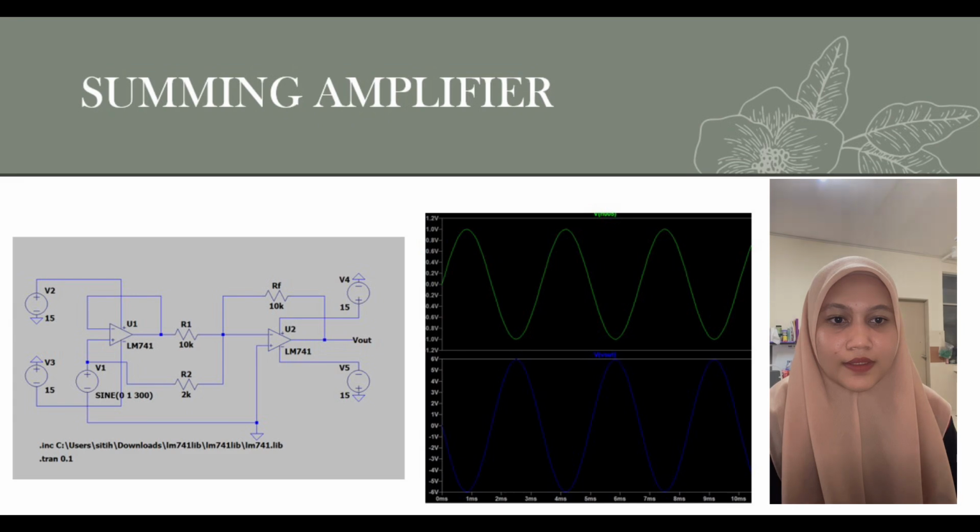Our analysis here addresses the high frequency limit. If the source frequency is increased too much, the output signal will distort because the op-amp's internal slew rate cannot change the output voltage fast enough. It is another crucial practical constraint.